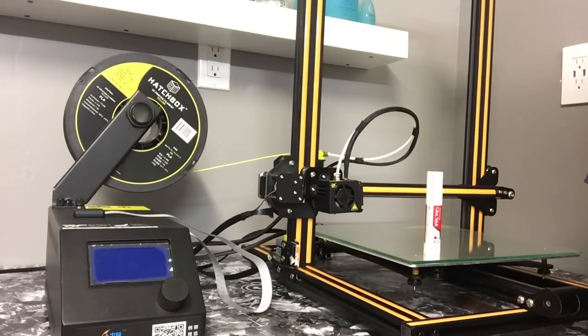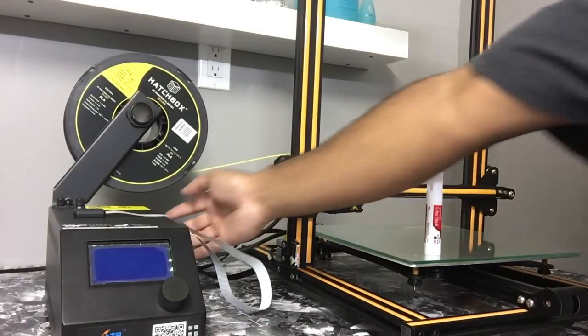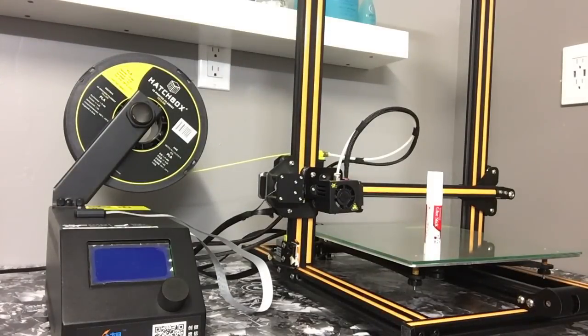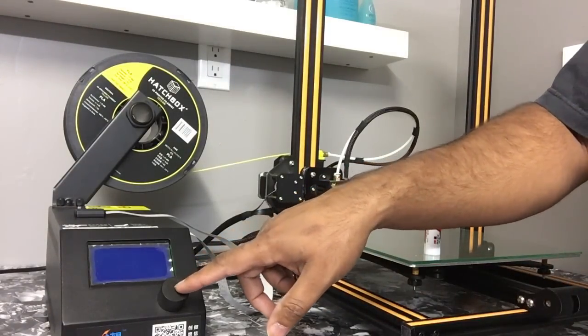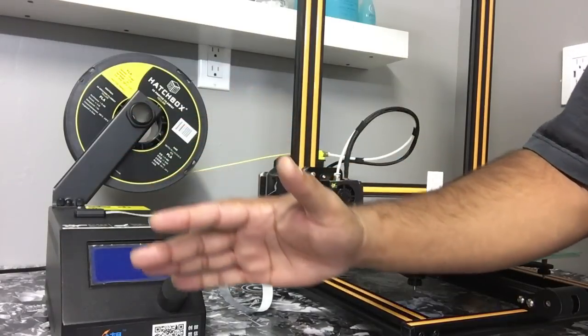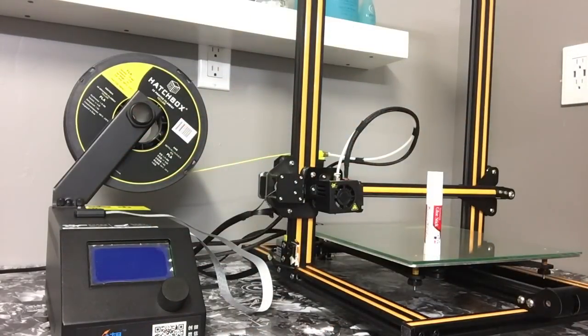But what might help you is, once you finish your print, most people just reach back here and boom, turn off the power. I used to do that. And then I read, if you just go into your menu, there's a cool down section on there. If you just do it and let it cool down on its own and turn it off, you're less likely to get clogging. It's not gonna prevent it, but it will help. Okay, so just keep that in mind.